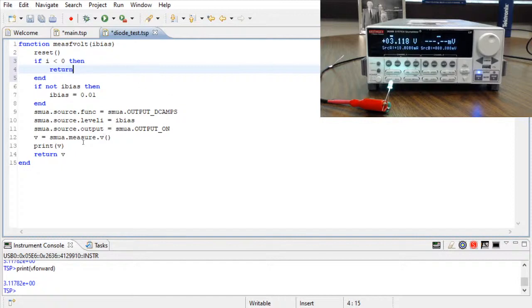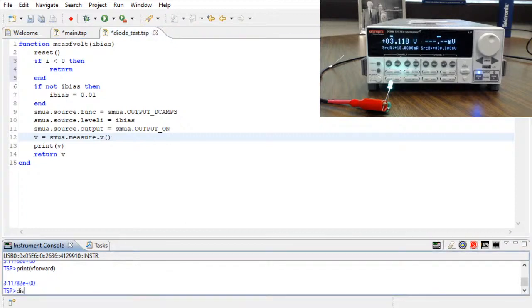So now we have this, let's try playing around with showing off these readings on the instrument itself. Let's try putting some things onto the display. There is, of course, a display library that allows you to control what's going on in the instrument. So, for example, let's try display.screen, and we'll set it to display.smua, another constant there. Now we're looking at just SMUA of the instrument instead of that 2-channel setup.